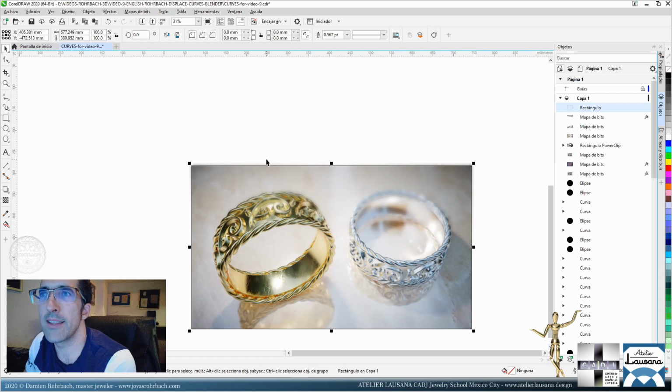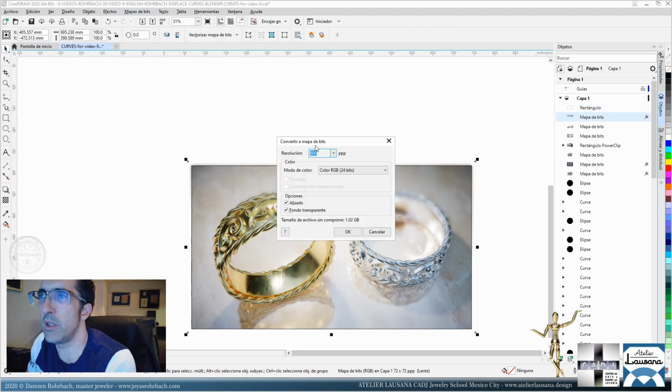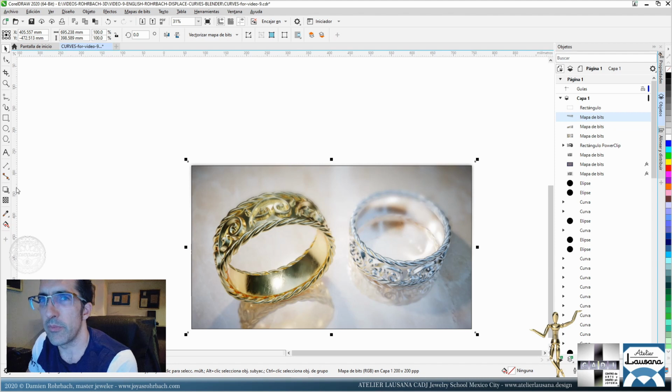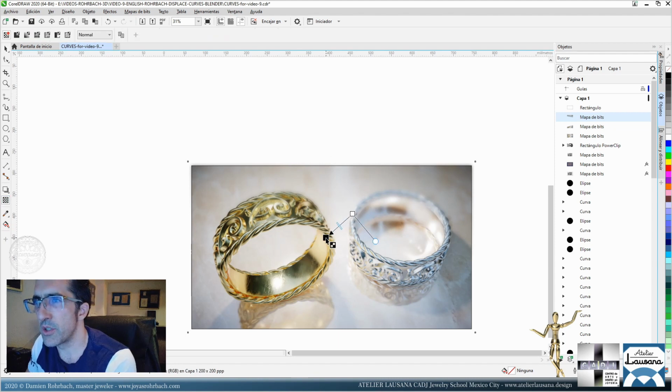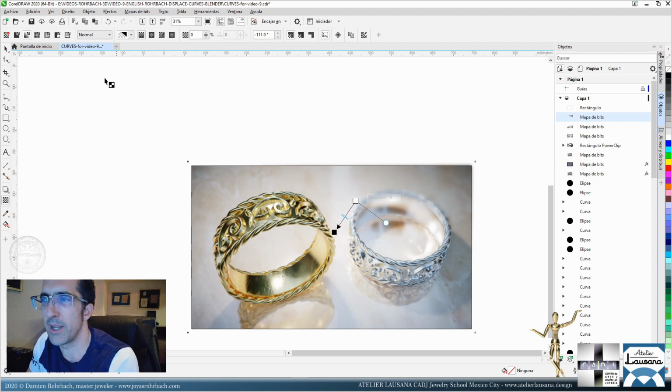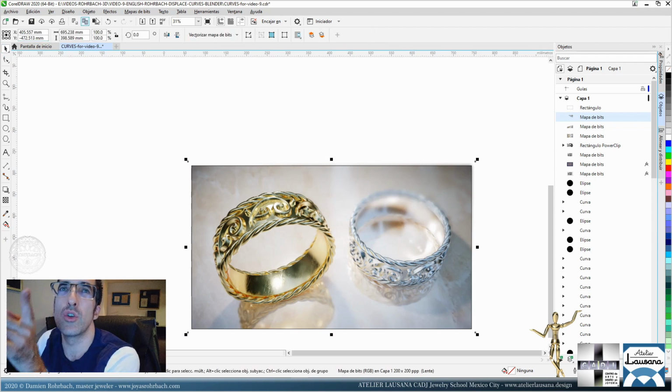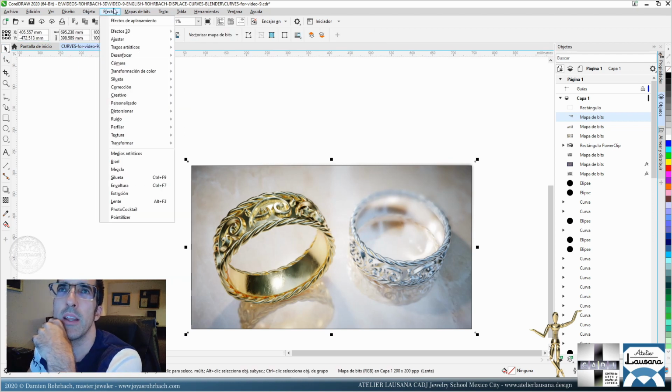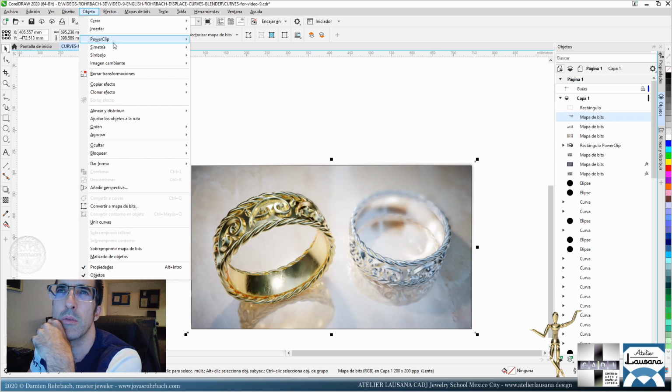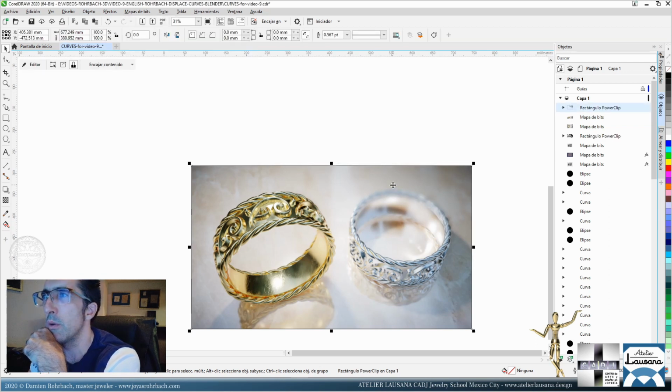Now that last image is going to get transformed to BMP. Let's go at 400 so it's not too heavy. That's pretty good. Because now I can change the transparency and remove that bad blur on the other sides. Just want more blur on the right side. And let's put that in the frame here. Object frame, power clip frame. There we go. We have all that.